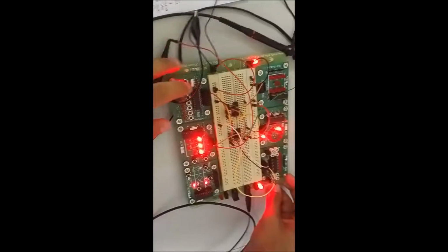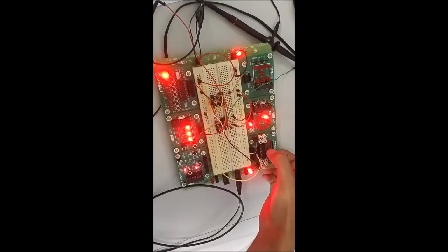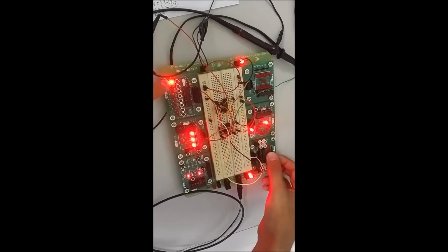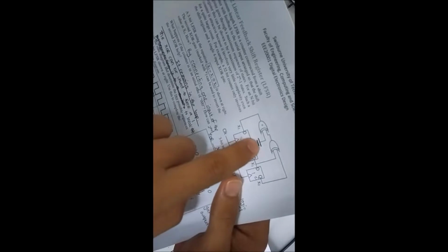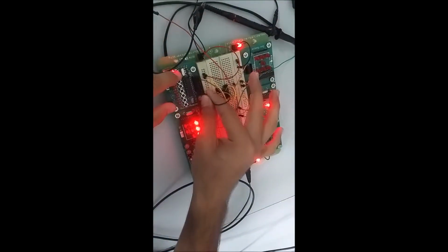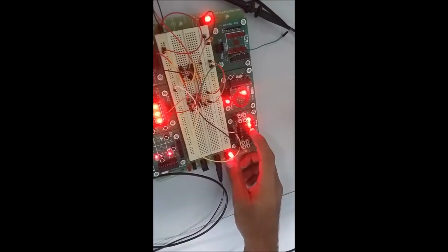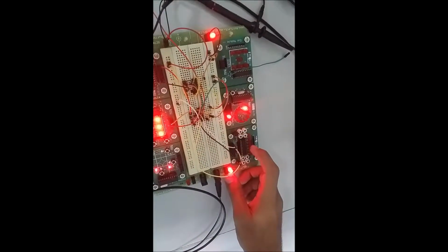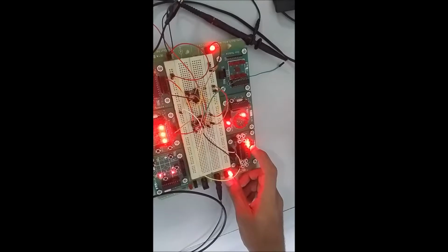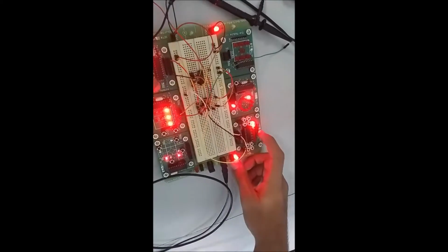Okay, as you can see here, it's looping from 0, 0, 0 to 0, 0, 0 infinitely. And how do we break this? As you can see here, the second XOR is connected to ground here, and we can disconnect this and connect this to 1 to break out from the loop. As you can see here, it's broken out of the loop, and this is 1, 0, 0, 1, 1, 0, 0, 1, 1, 1, 0, 1, 0, 1, 0, and it's going to keep on looping.